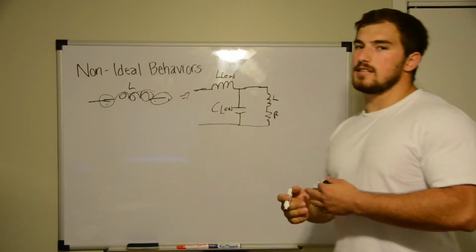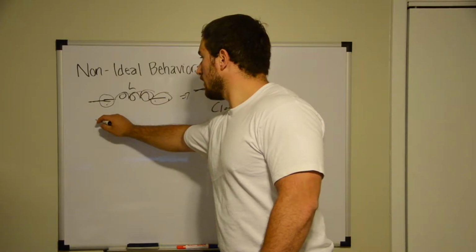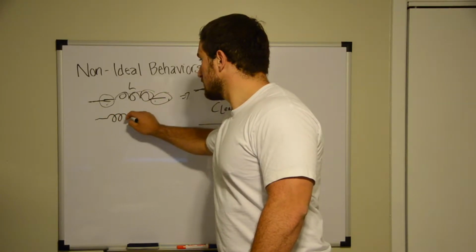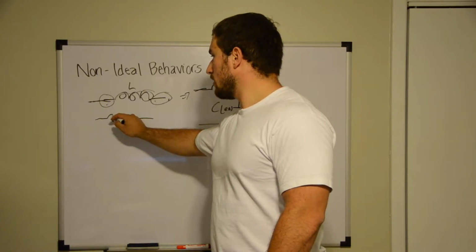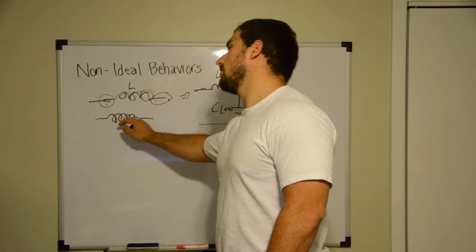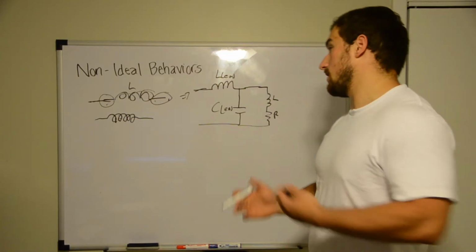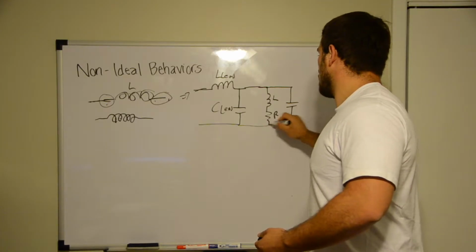We're also going to get some parasitic capacitance, because if you look at an inductor, it's basically loops, and the current in this loop will cause some displacement currents in here, and that's a parasitic capacitance that we just are going to have to also include in here.